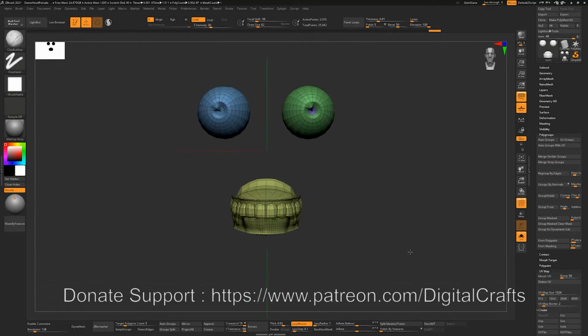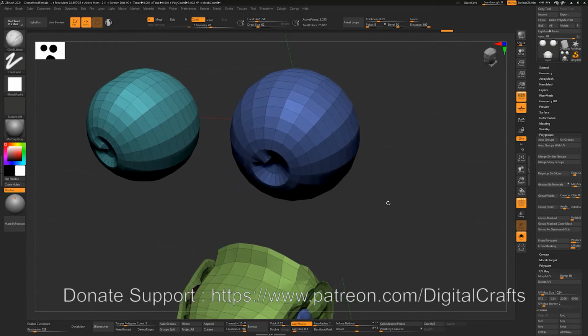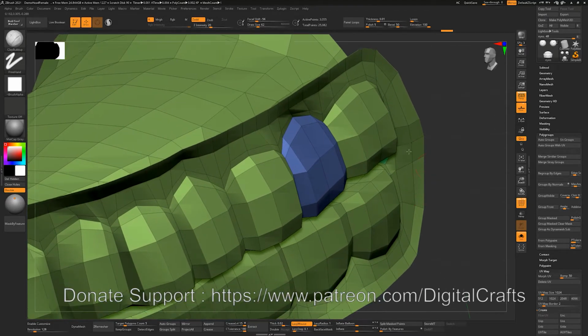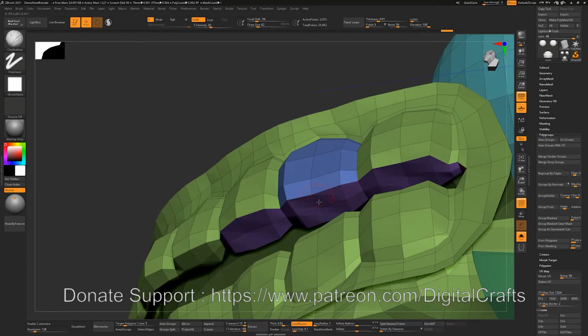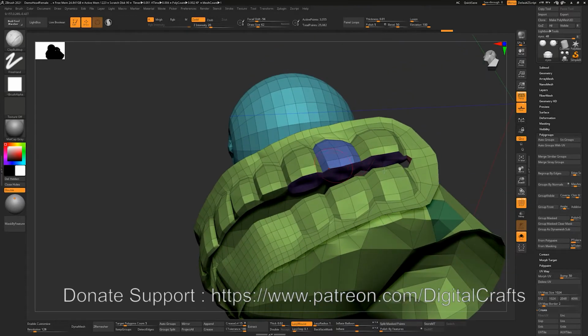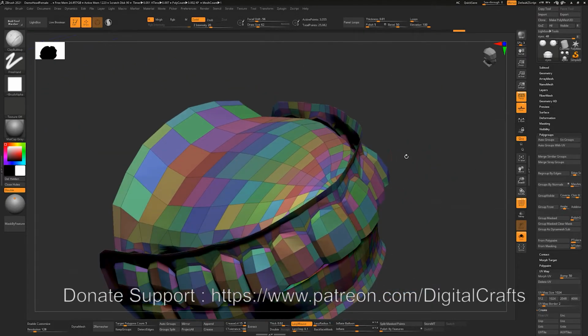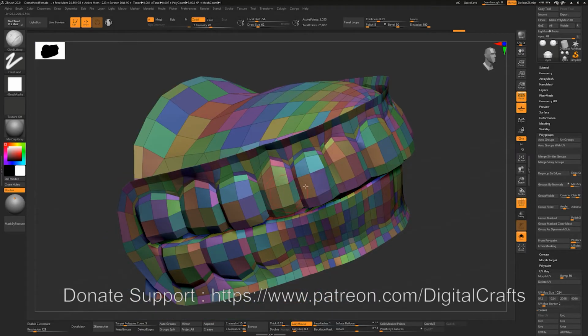So we can also do a group visible or the group by normals. For example, if I do a group by normals, if the normals are facing the same way, then it won't be grouping. For example, these normals were different than these normals, but I don't use group by normals often because sometimes it gives weird results like it's giving here right now. So I reduce the average. And yeah, now it groups by normals because every one of the faces has a normal difference of at least one, so it will group them by the normal angle.